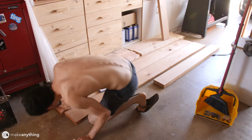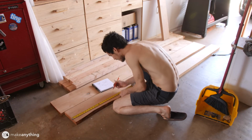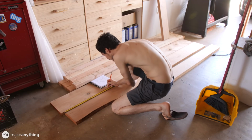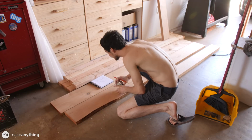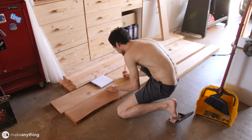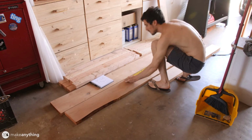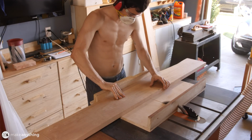Alright, so now that I'm pretty confident with my CNC, the next thing I have to do is build the stock, or the raw wood piece that I'm going to cut my pattern out of. And instead of just having a huge sheet of wood, I'm trying to be economical here and use as little wood as possible. So I'm actually going to first construct a rough version of that hole number 1, just with a slightly wider border, and then I'll cut my shape out of that with the CNC after the fact.